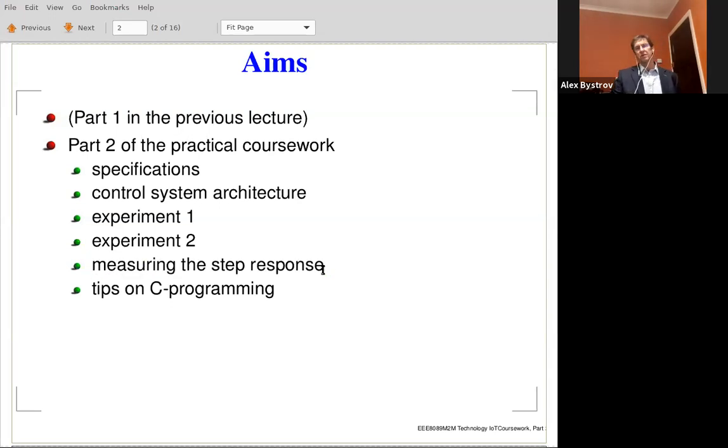How I suggested to measure this: instead of applying the step function at the time 0 to the system, I suggest to alternate between 1 and 0, or 2 and 0, 2 and 0, 2 and 0. Alternate sufficiently slowly, and then you will see how the system transitions. And the transition which is of interest for us is the transition from the value 0 to the value 1.